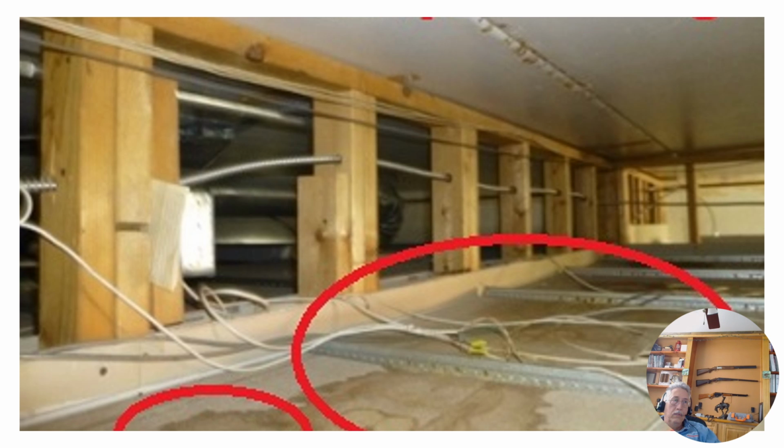When I train people to do inspections, you have to look above the drop ceiling. I know a lot of organizations say you don't have to do that. That's one of the dumbest things I've ever heard, in my opinion. You find a lot of trouble above the ceiling. So here, we saw some additional watermarks. You can see the watermarks on the ceiling tiles, and you can see wire. There's just Romex wire laying all over the top of this ceiling grid, and it's metal, and you got a splice right there, junction with no junction box on it.